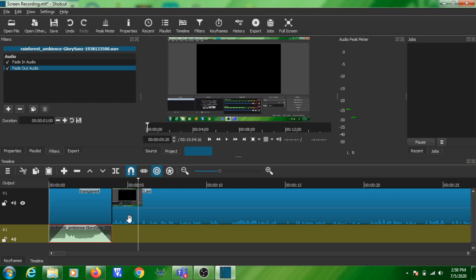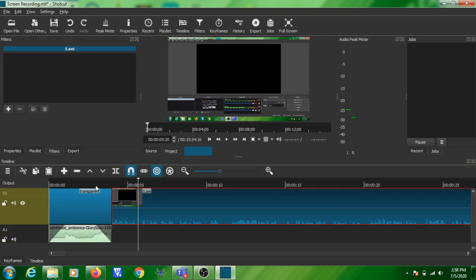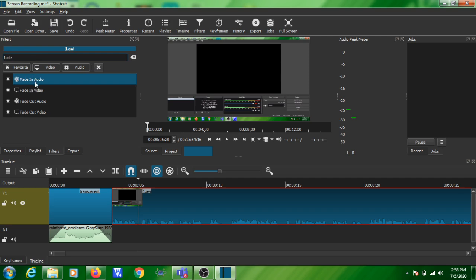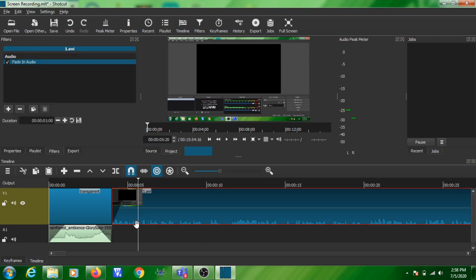So let us take, you are clicking on this video, right? Then you are going to click on this and select fade. So here you are going to take fade in audio again, right? Fade in audio for this video track. So now you have given a 1 second fade in. If you want to change it, you can change it to say 2 seconds. So now you have added 2 seconds.